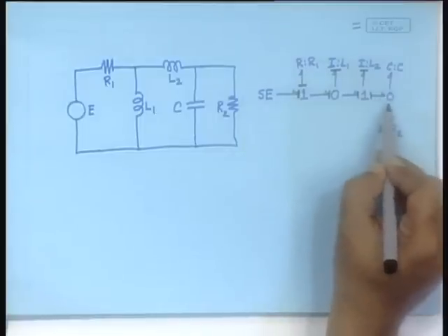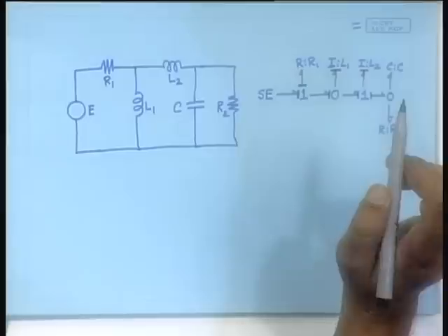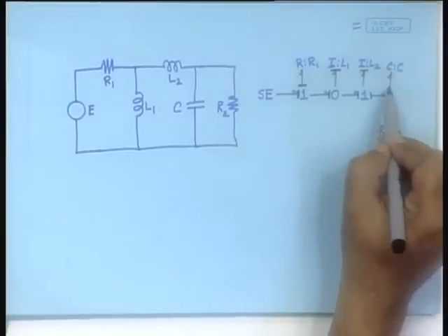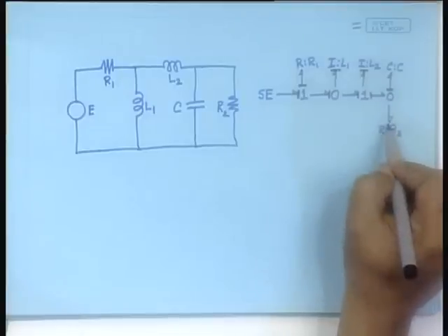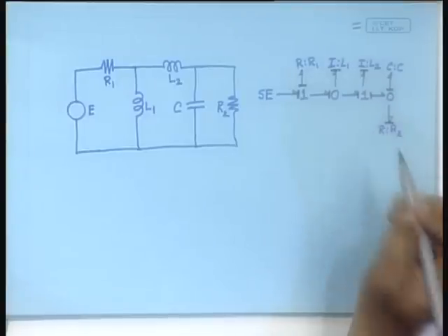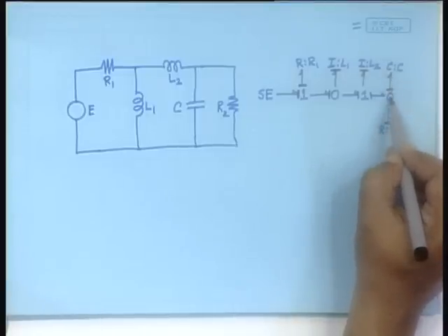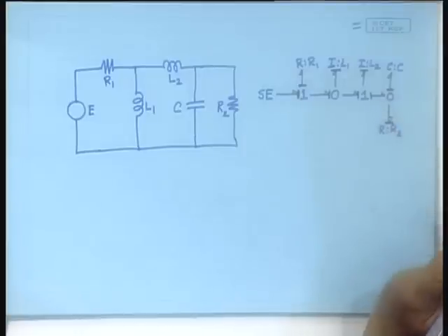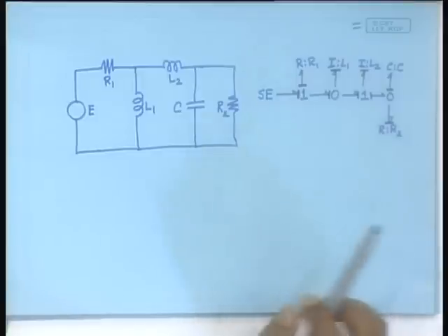Now you come to the last one, 0, which has received the flow information, but you need the effort information. Normally the C element would create the effort information and bring it here, and therefore the moment you do that, the other ones are immediately causal, because this has brought in the effort information, and effort information will go out through these two, which is what we are doing now. Okay. So all these bonds are now causal.